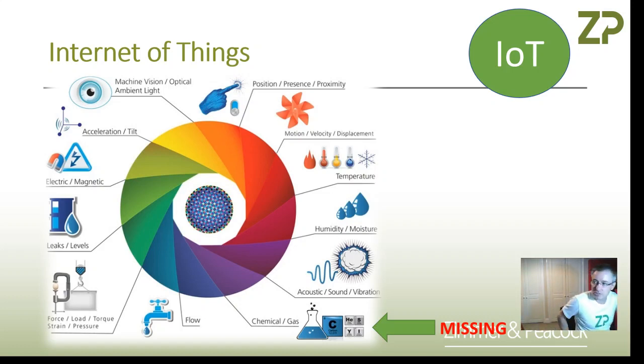I've got a humidity and temperature sensor. Let me just grab that, for example. So this is a humidity and temperature sensor. Very relevant at the moment. The sensor itself is a little dot here. You've got a lot of people talking about, unfortunately, COVID-19 and the air quality and how many people are in a room. And if you want to know how many people are in a room, one way of doing it is actually measuring the humidity in the air. People, when they breathe out, they deliver a lot of humidity. So if you want to know about the air quality in a room, temperature and humidity is not a bad thing to be measuring. It's quite easily done.